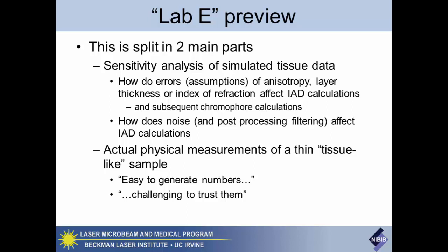And we do that for every single measurement. So even if a sample in a certain location may block some of the stray light, we measure that every single time. For the zero, it's just a straight subtraction of your measurement minus your zero. So that shifts it. And then for your calibration, it's the ratio of your 100%. So your measurement divided by your 100% becomes your calibrated spectral data.